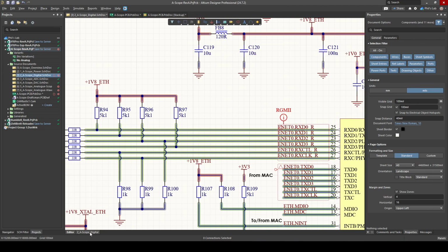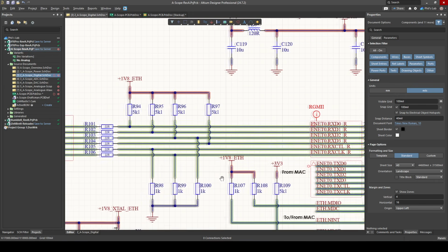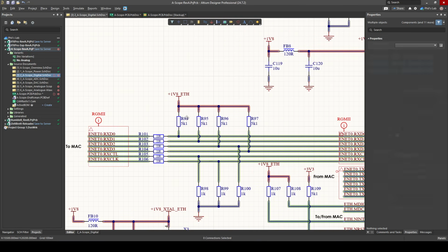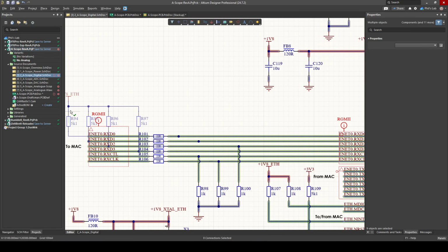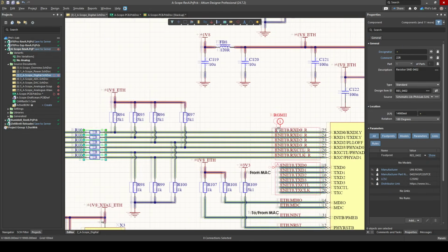Keep in mind this Altium view, if I click on the bottom left hand side, I do actually have variants, so that's why it might look a bit odd that all of these resistors are populated, some of them actually aren't. But also the placement is important of these strapping options. Now we could place these strapping options very simply, for example, on the left hand side of these series resistors. But keep in mind these are series termination resistors, so they will be placed close to the driver.